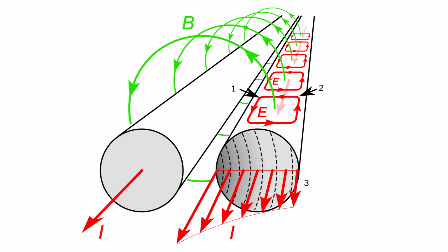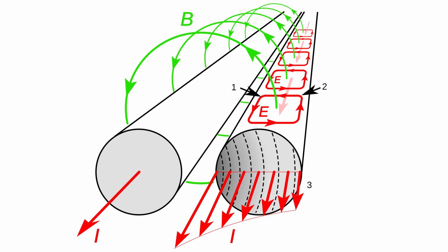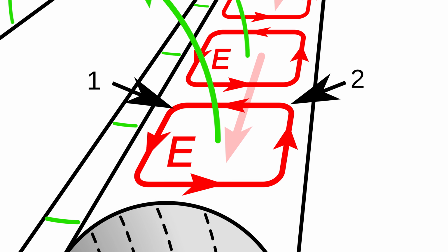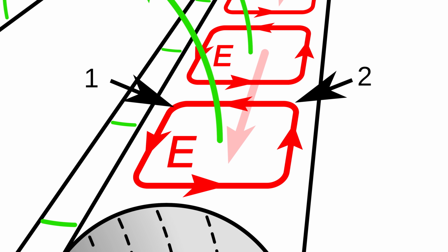Another common problem in printed circuit board routing is the accidental creation of unwanted antennas. Whenever current flows through a wire, some of the electromagnetic energy will propagate into the surrounding space. Some of this energy can be captured by other wires inside the same device and interfere with its operation.